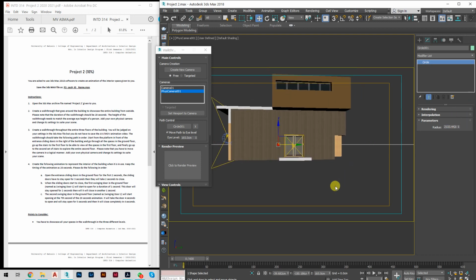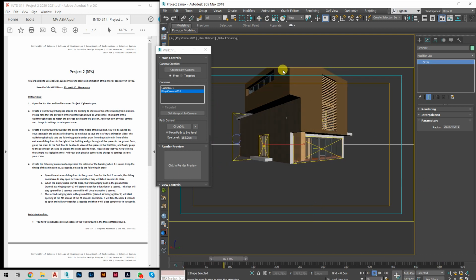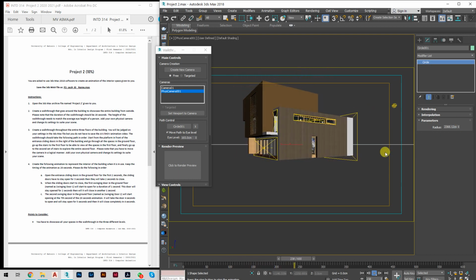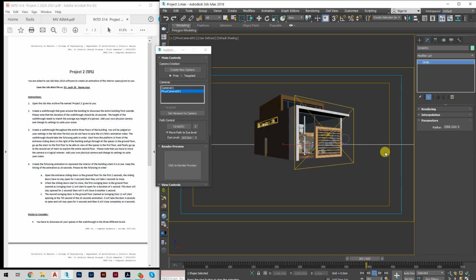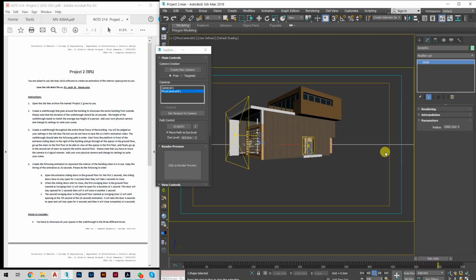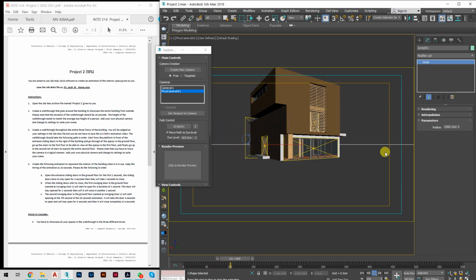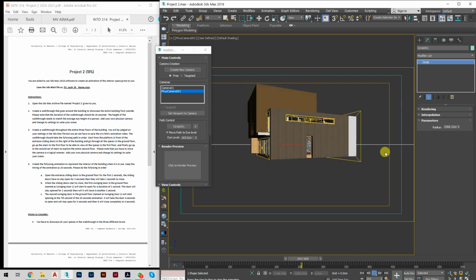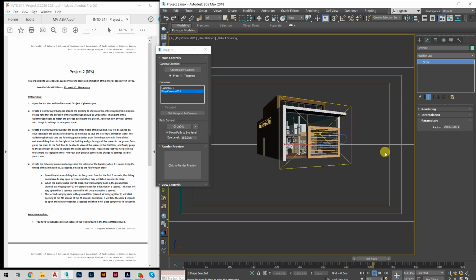That's it. This is more than enough. Now when I click on play, I can see the building. If you want to view this part as well, make sure that you make it bigger. This is because the requirement is for the camera to be at eye level, so this is 165. Otherwise, if you're working on your projects for design or any other projects later on, you can move it to 200, 250 if the view is okay.